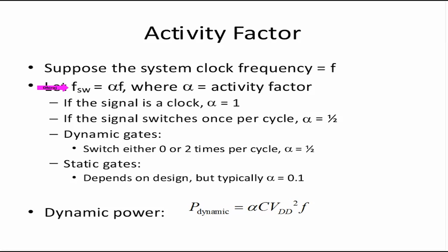What happens to data signals? For data signals, we would be concerned about the clock they are related to. For example, we write in an always block, always at posedge clock. We capture some data on that clock. The meaningful clock for that data is the same clock it's capturing the data on, not any other clock. Let's say your design has multiple clocks. Each data signal will have a relative clock, and the frequency of that clock should be taken into consideration.